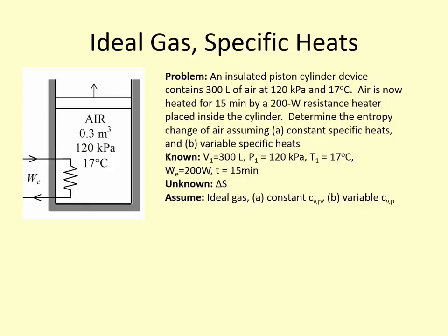No heat transfer, okay? So adiabatic is different from isothermal. Adiabatic means no heat transfer, but just because there's no heat transfer doesn't mean that the temperature stays the same. So be very careful about that assumption.